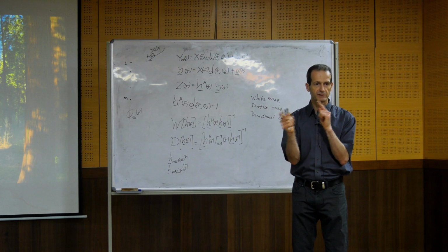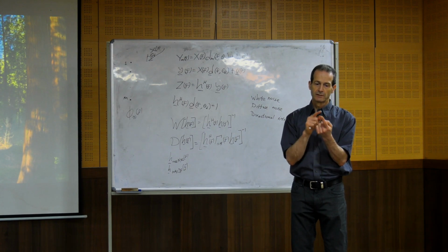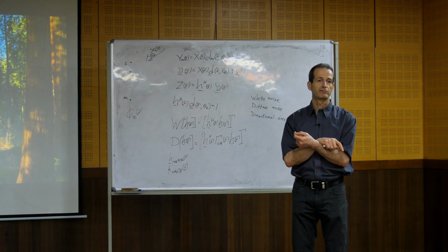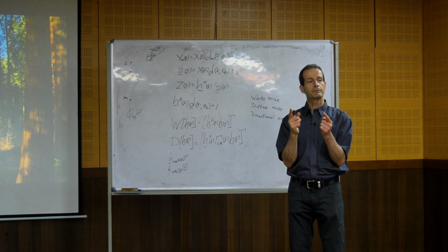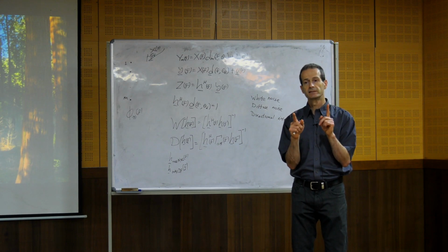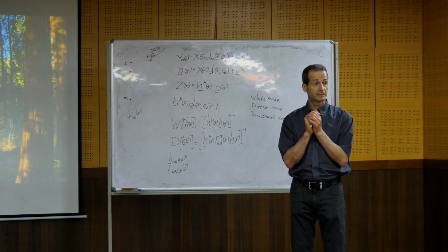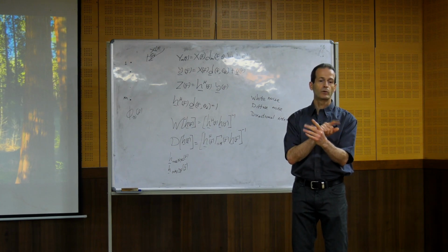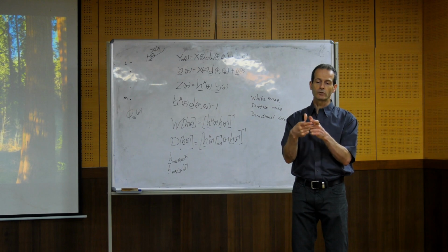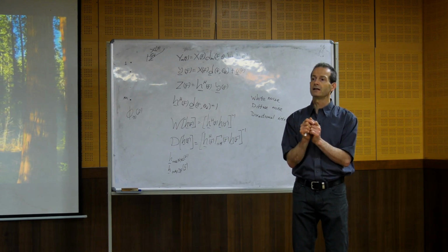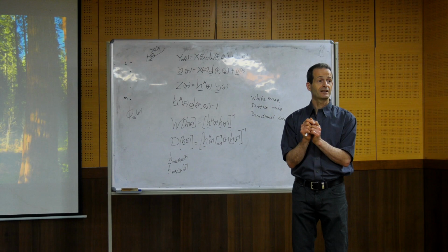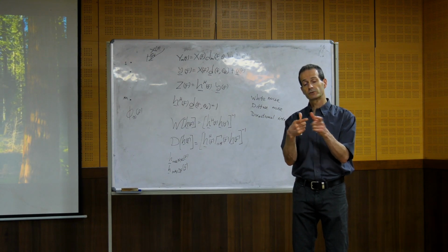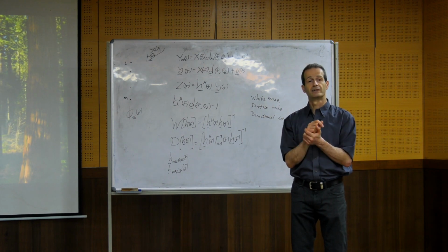So if you have differences between sensors, the output signal will depend on the sensor, not only on the propagating wave. So there can be magnitude differences, there can be phase differences. The electrical signal will not correspond to the phase of the propagating wave.